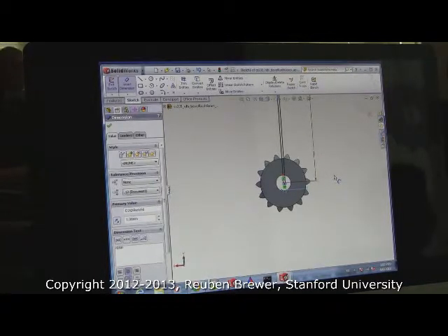Whenever you can, if it's something where it's just an arbitrary number, pick round numbers, because then later if something's not working, I'll show you how to measure things. If something's not a round number, then you know it's not your number. So I could make, this is just a gap. Basically this is a clamp. We're going to use a screw to clamp onto a shaft. I could make that space whatever I want. It could be 0.939. But then if I make it 1 and it's not 1, then I know, hey, something's wrong. Also, when you measure with calipers, you don't have to go back and look at your CAD. You know if it's not a round number, it's not correct.